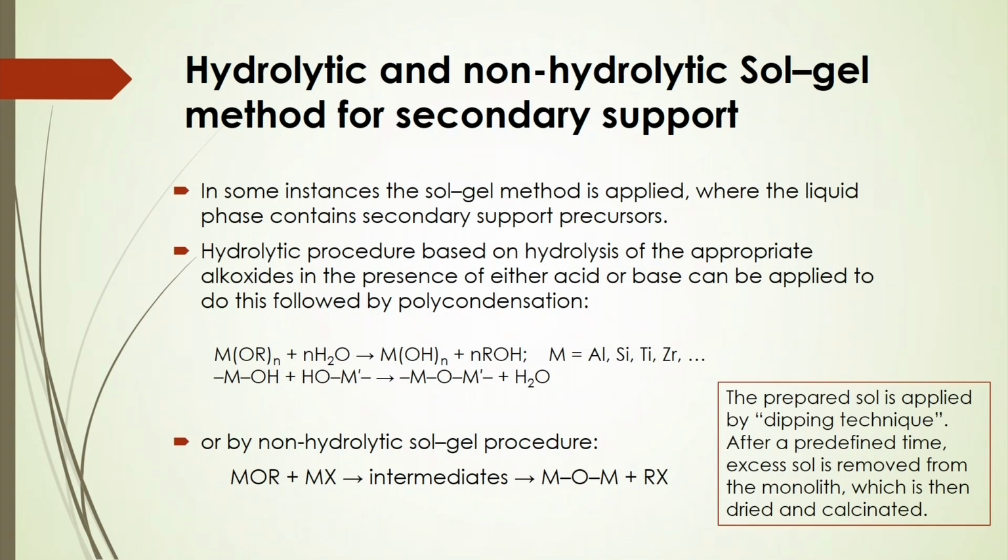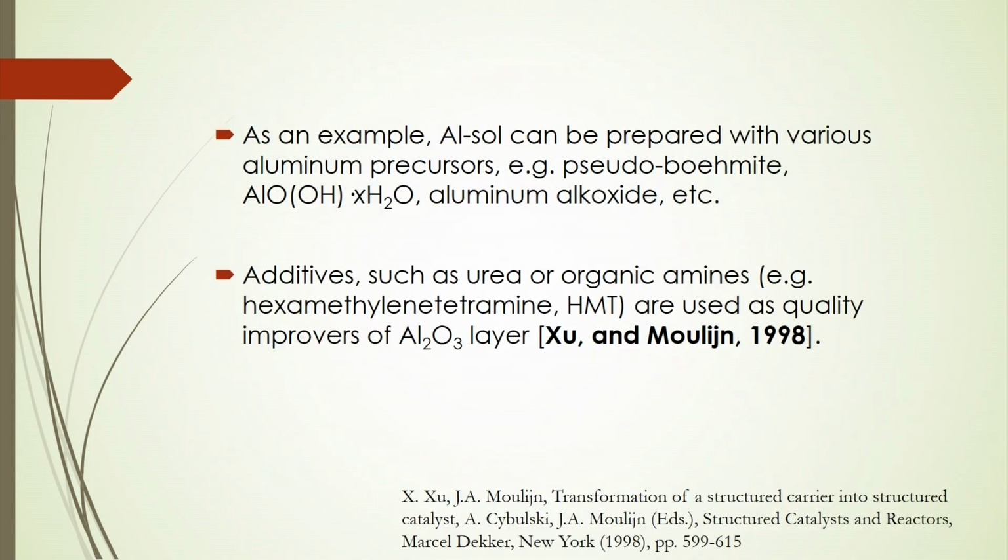You can do either this method, or you can do it by the non-hydrolytic sol-gel procedure also. The non-hydrolytic sol-gel procedure is given here. In this case, the prepared sol is applied by the dipping technique, and after a predefined time the excess sol is removed from the monolith, which is then dried and calcined to get this secondary support.